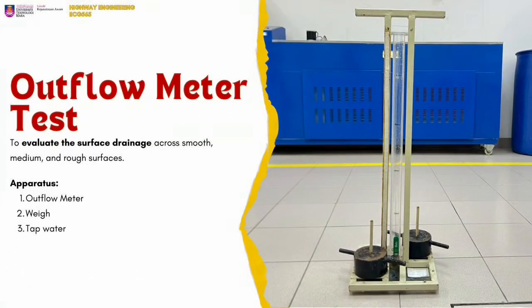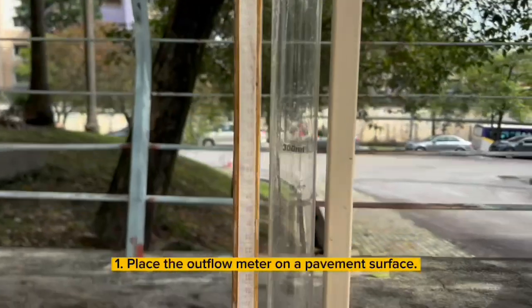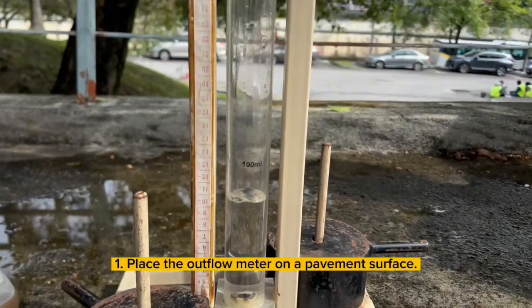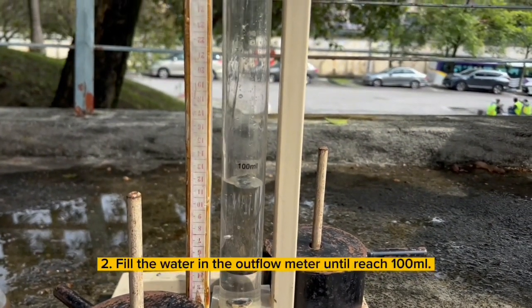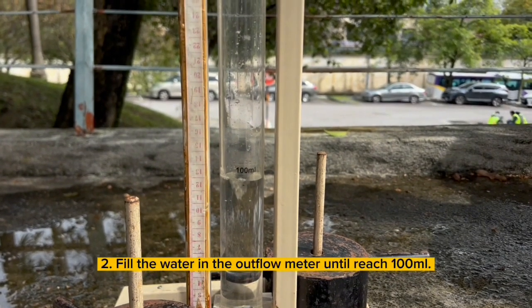Next is the outflow meter test. This test is to evaluate the surface drainage across smooth, medium and rough surfaces. The apparatus used for this test is an outflow meter, weight and tap water. To conduct this test, first place the outflow meter on the pavement surface. Then fill the water in the outflow meter until it reaches 100 ml.